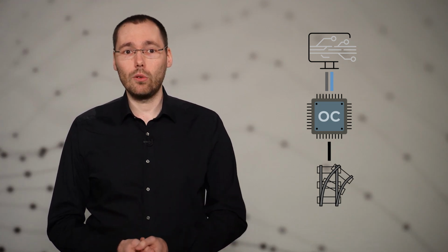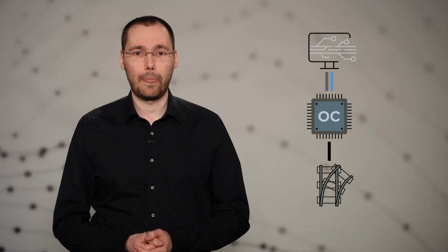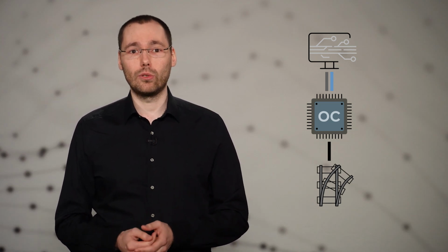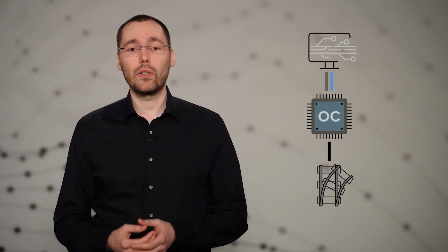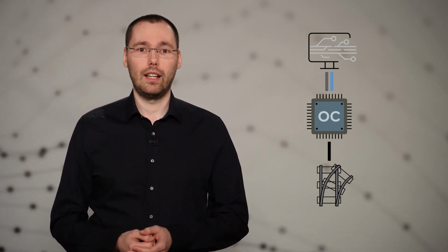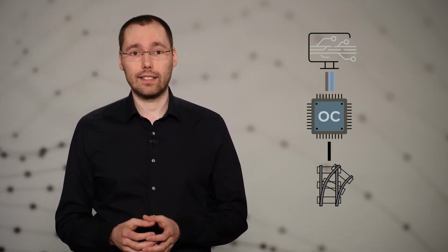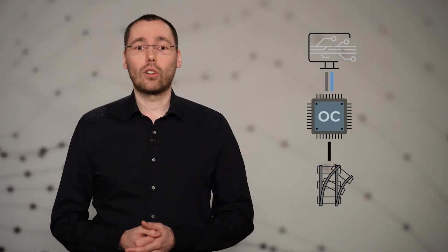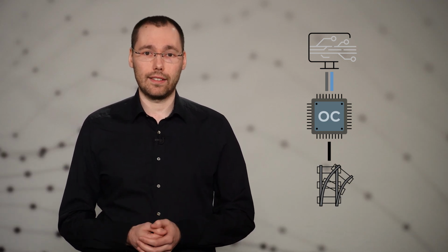This concept is known as hardware-in-the-loop testing, or HIL in short. With HIL, I can validate the system's behavior and ensure that hardware and software work together as intended across various scenarios. As the simulation provides precisely known initial states and straightforward means of manipulating its behavior, the concept offers a high degree of repeatability during the testing phase.